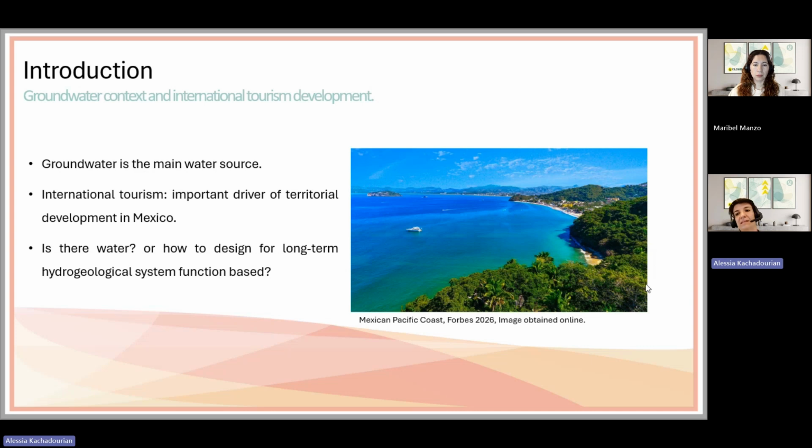Water capacity is often presumed from very light and limited hydrogeological studies. And in addition, when the projects have their own groundwater wells, their actual performance is assumed to be perpetual, and there is no evaluation of the groundwater dynamics and well sustainability.